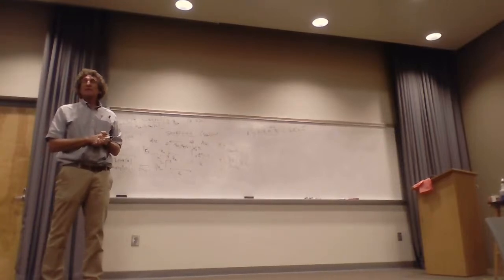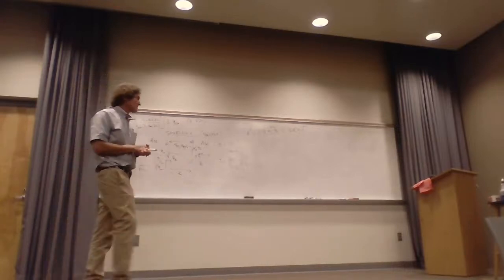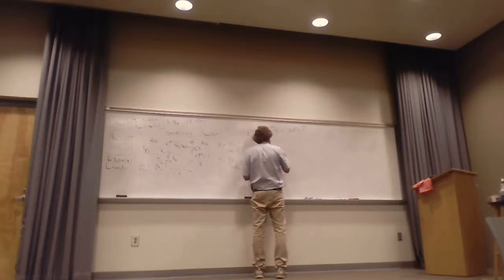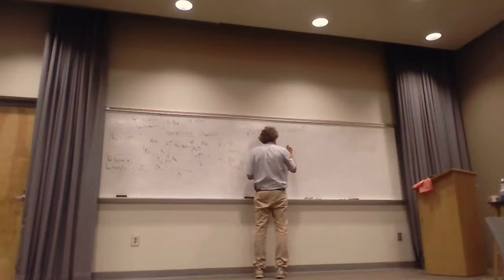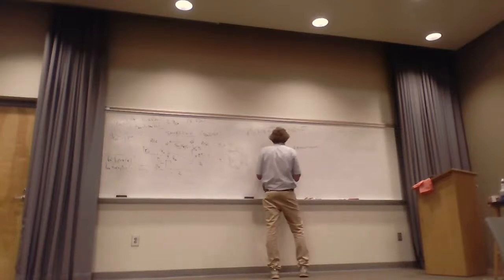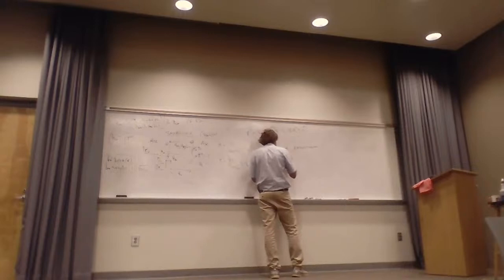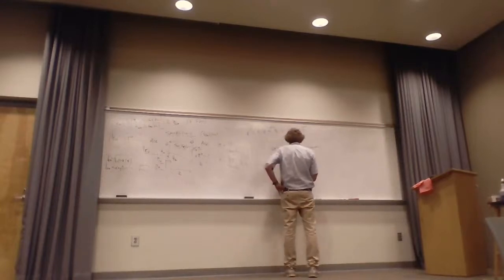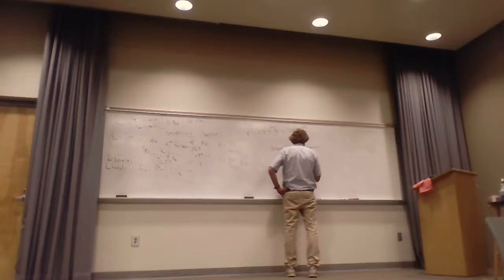With shields, they typically talk about shielding effectiveness. So shielding effectiveness, or SE, is equal to 20 times the log, that's log base 10, of the incident electric field divided by the transmitted electric field.